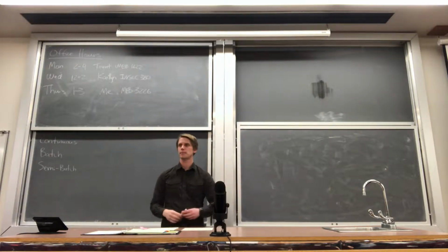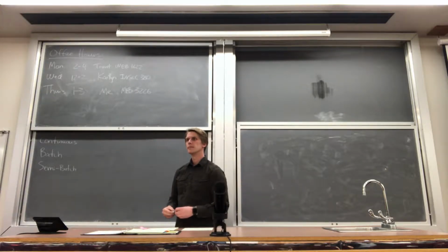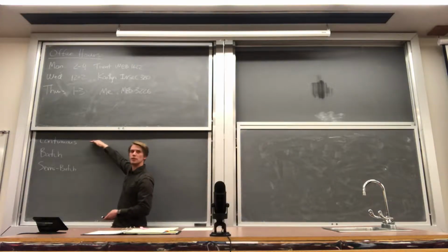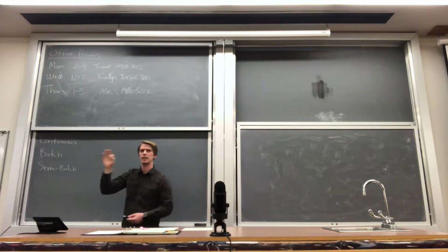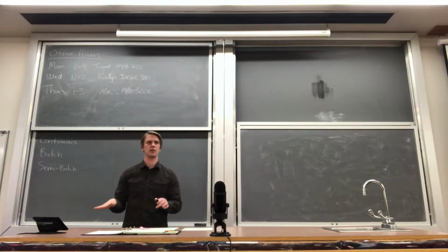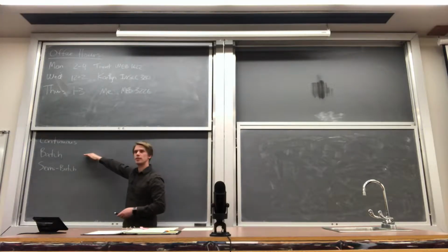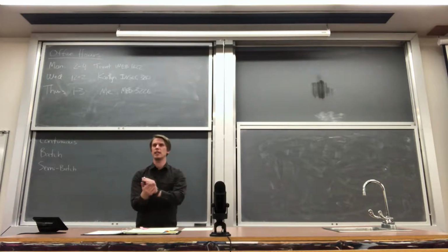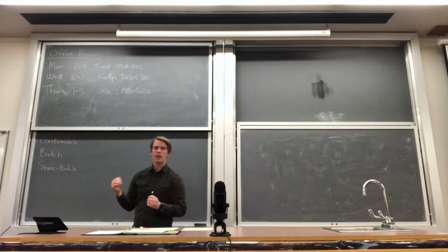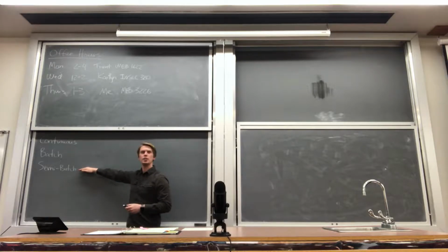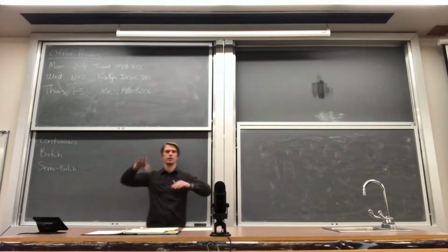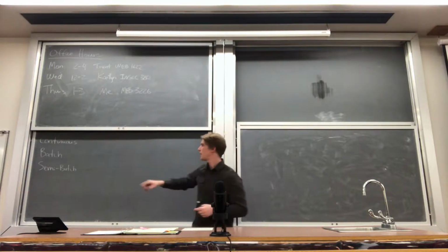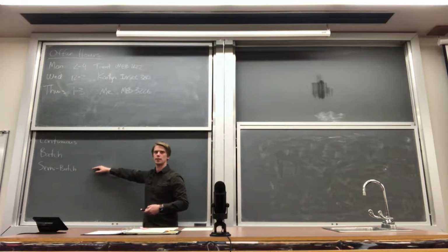So it's just a time where you have mass leaving the system after you put mass into the system? Yes. In a continuous process, a good way to think about this is that the mass is entering and leaving continuously at exactly the same rate. Nothing is changing as a function of time. In the batch process, nothing is entering or leaving as a function of time. You put everything in, you seal it, you wait, and then you take it all out. So anytime that something is entering or leaving and the total amount in the system changes, that'll fall into a semi-batch process.